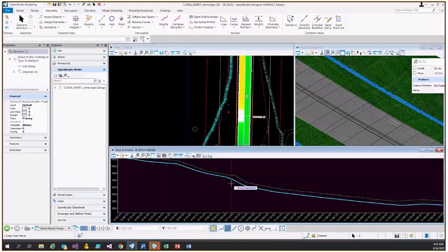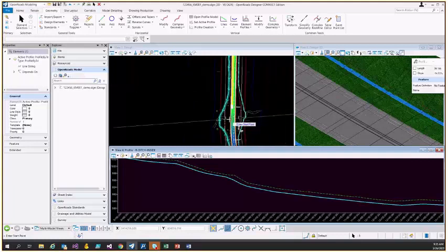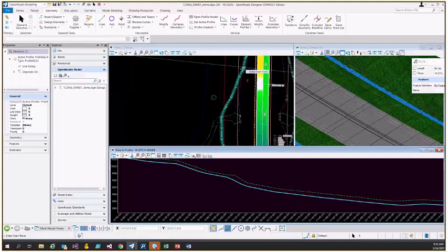I think what we've always done in the past, from my knowledge, I'm not an expert on this subject, is just do ditch profiles off our center line. So doing it this way, you're technically getting a little bit more exact, because when you project this onto your center line, this is a longer length on your profile of your ditch.